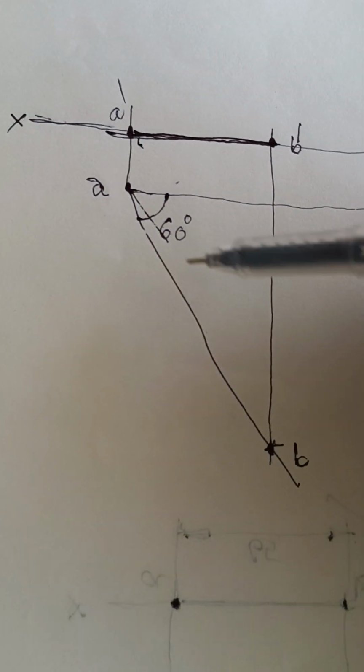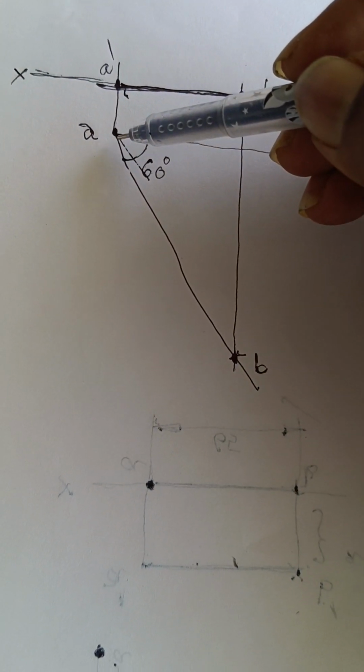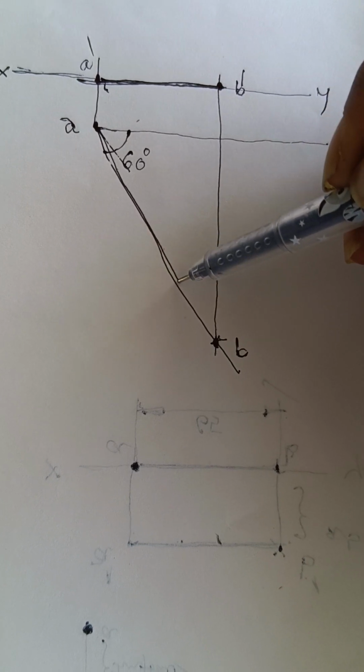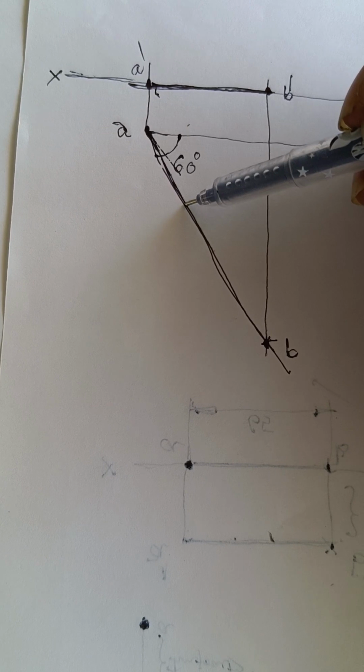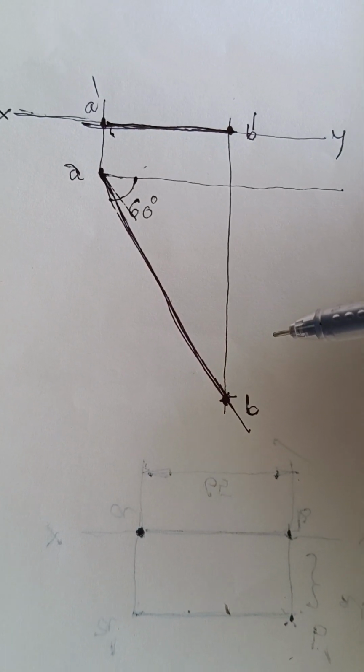line AB. In the horizontal plane below the XY reference line we get, in between the top view of A and the top view of B, a line which we need to darken by making use of a B pencil. This is AB.